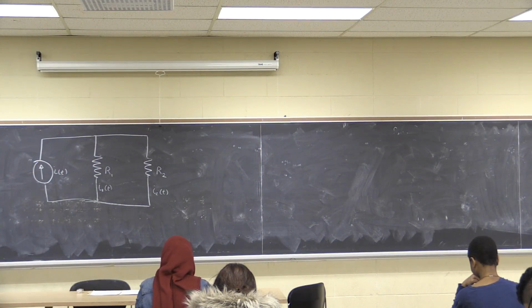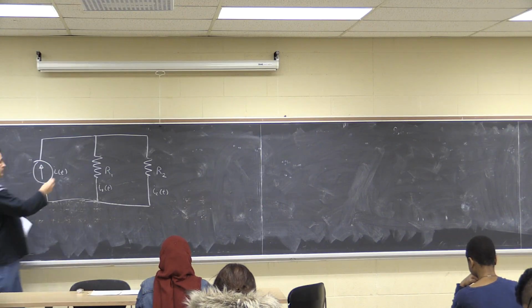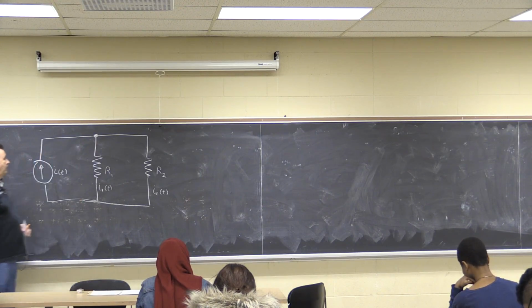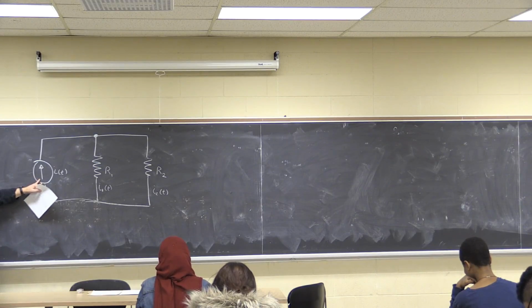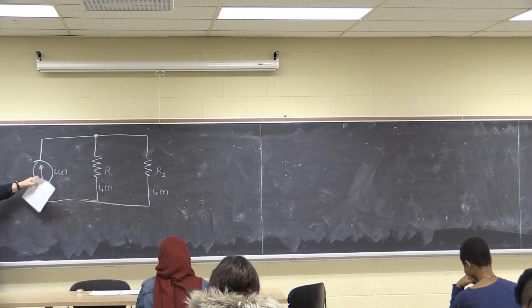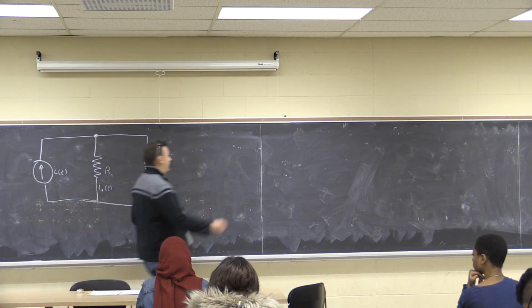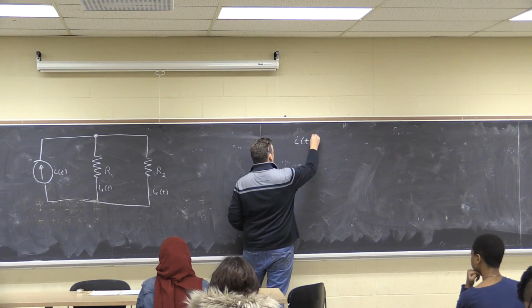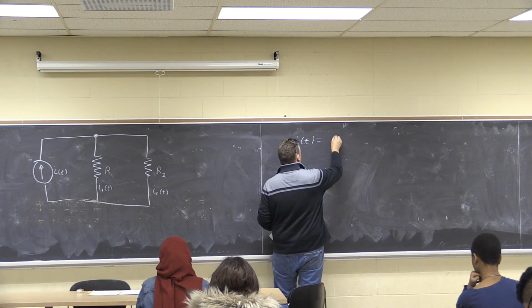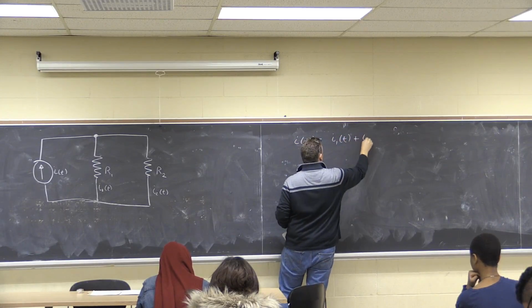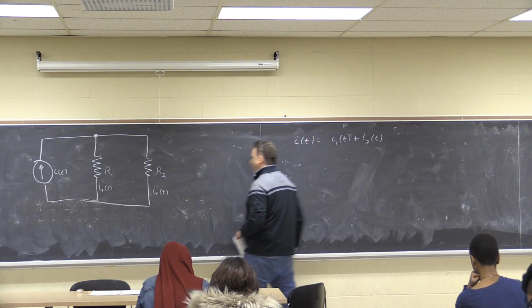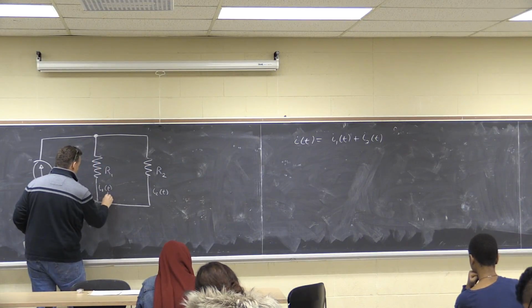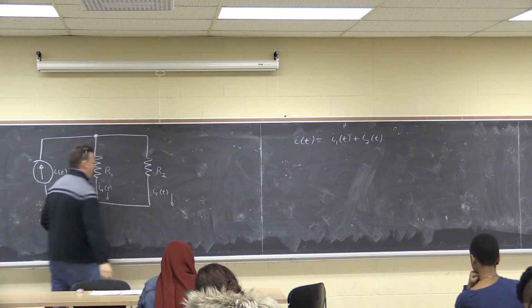So it's current, so it's flow of charge. So when I apply Kirchhoff's current law, I'm going to look at a node and sum all the currents into or out of that node. So let's look at this node at the top. Well, I know the current flowing in, delivered by the source. This is an independent source. It always gives the current I of t. So I know I of t into the node must equal I1 of t plus I2 of t. And just to clarify, let's say that's flowing down. That one's also going to flow down.